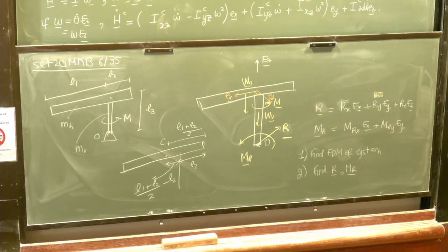And then F equals m a_C, and you calculate a_C this way. Why is that alpha zero? Only initially, if it's starting from rest. I just did it initially because I wanted to get a final answer instead of a long equation, and make sure I did it right. Okay, cool. Then you can find the reaction force, and they only want the horizontal component of it, x and y. Okay, alright, good job.